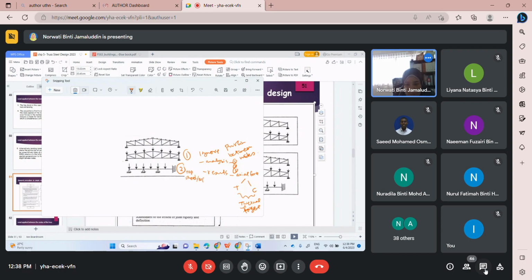Okay, the next step, just consider the top chord or rafter. Just consider the top chord with the actual load condition, but just half only, half of this rafter, because this is symmetrical, right? Just perform at half of it. Okay, with the actual load condition, where the first purlin is at knot. This is support, right? Support.